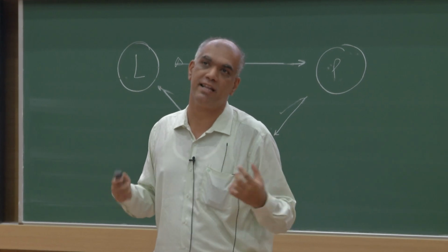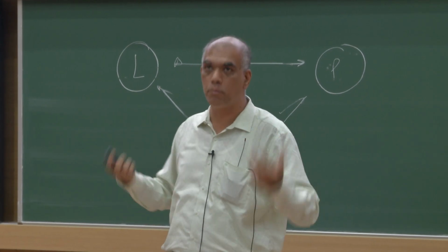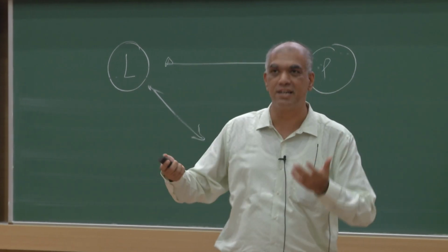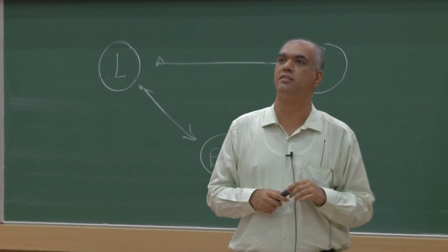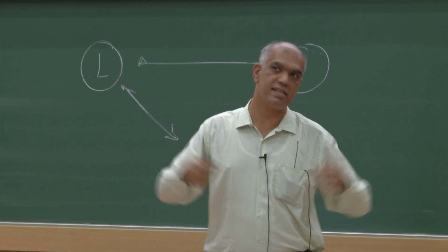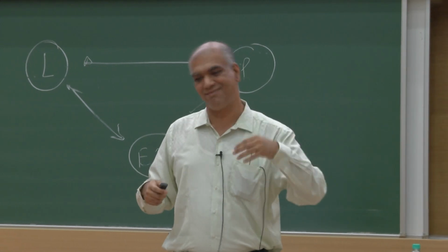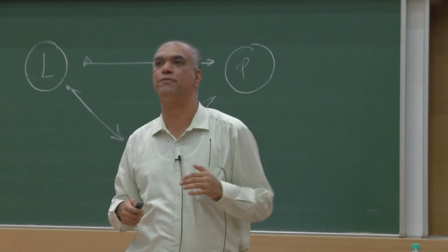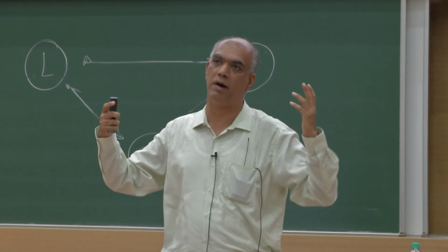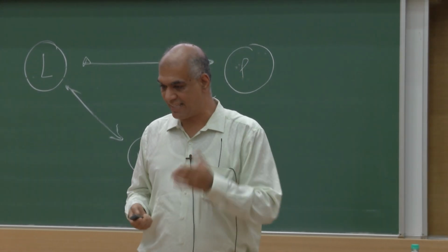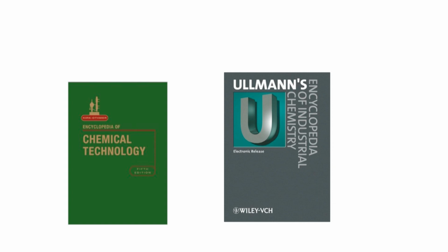This is not a mathematical thing. These are more like heuristics, thumb rules, and a good design project is going to use a lot of them. So suppose you have a certain pressure and you say, okay, I'm using a 3-stage steam ejector. And suppose the examiner asks you, why did you use it? And you say, okay, I looked it up. Now that demonstrates a higher degree of thought than just picking a single vacuum pump, which may not even work for that level of vacuum.